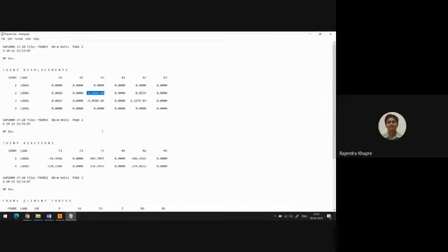But as far as rotation is concerned, the rotation is about the y-axis. So here R2 you will find this value, 0.0134. This is the rotation, and the unit here is mostly radians. Okay, so you can check these values with your solved problem in the class.